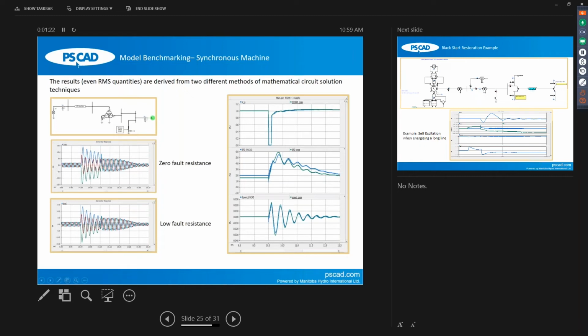This is when, in the model, I used almost zero fault resistance. Now, if I add a very small fault resistance, like see, the blue curve also decays and the fault will be cleared after 0.1 seconds as you expect, as you define in this fault time logic.